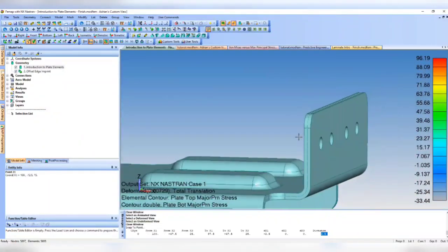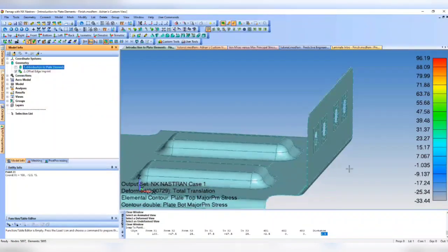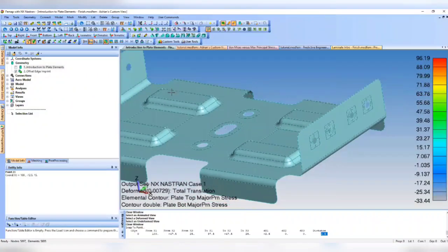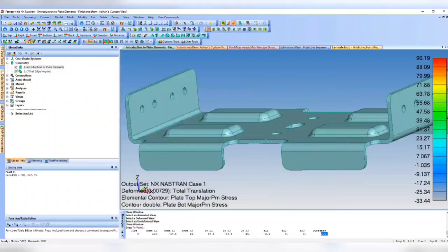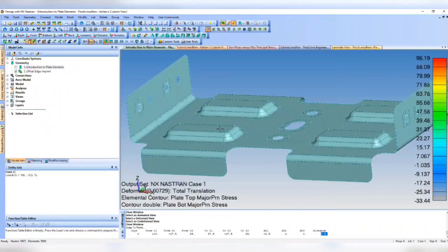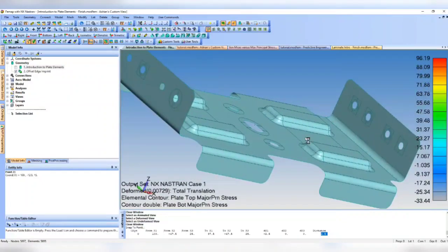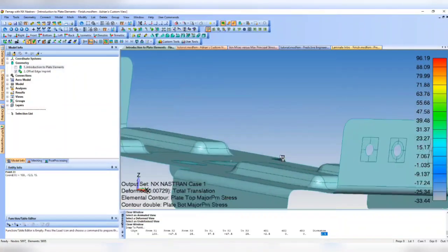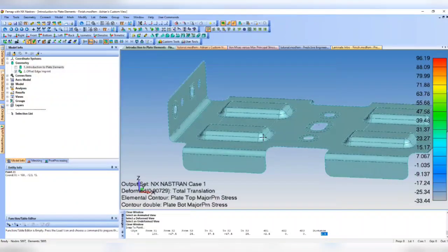So when you model shell elements, they're 2D elements, so you always want to mid-surface. I don't know if you guys saw that. This is the CAD model that you get with thickness. I already mid-surfaced it, but basically, as the name implies, you create surfaces along the midplane of your 3D CAD model. So you can see that it's now 2D, and within the properties of the shell element, we're going to define the thickness.